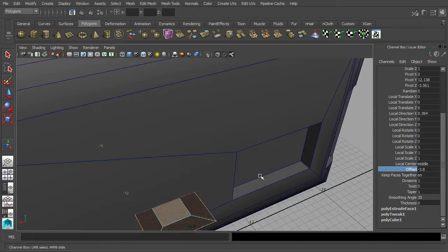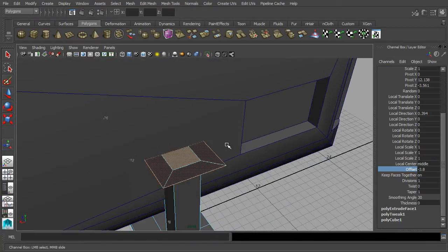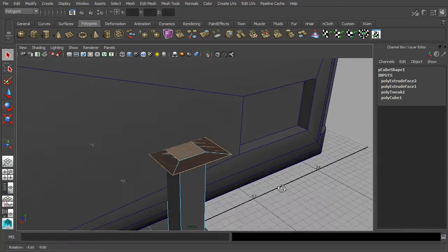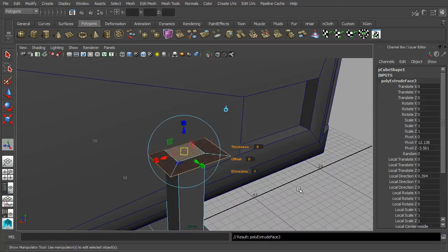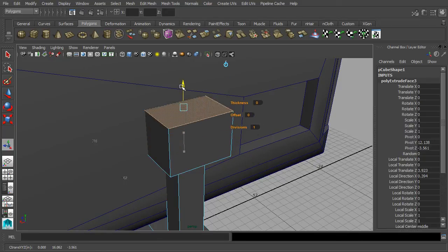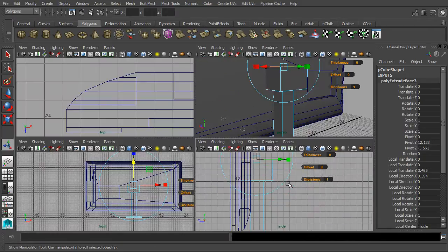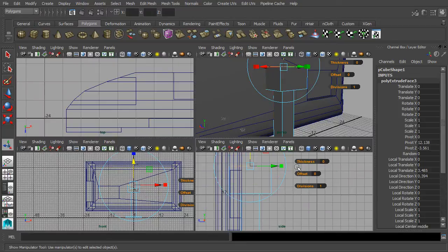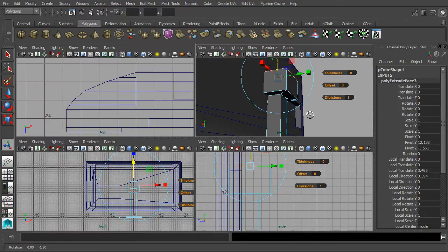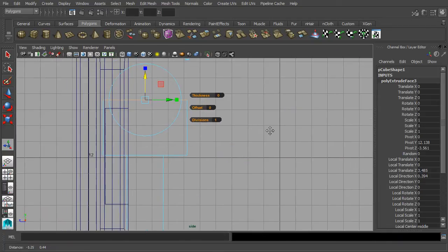Great. All right. And we want to select the top face only now. Go into the select tool and click just to make sure you selected only that top face. And do another extrude with the G key. Pull that up. Cool. Check it in the side view here, and what we see is a perfect right angle there. We can move this whole structure forward and back. That's best done using Vertex component mode. So let's do that. We'll do that in the side view here.